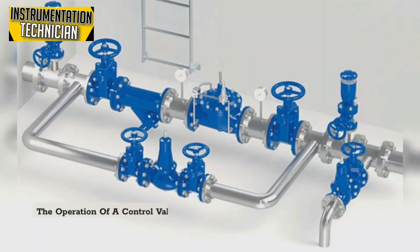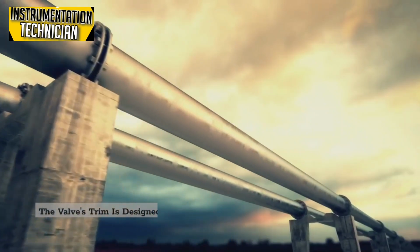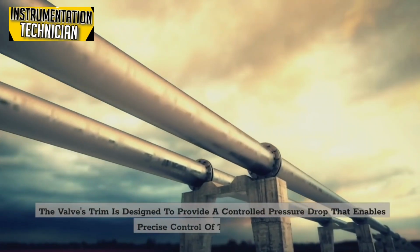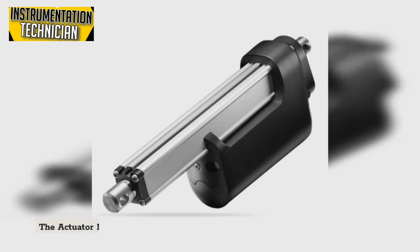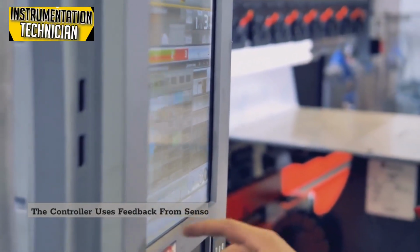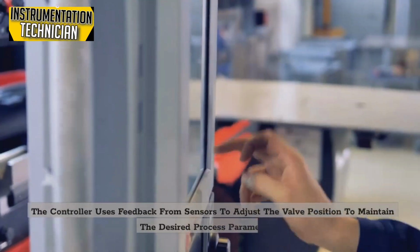Control valve operation. The operation of a control valve involves a complex interplay of fluid dynamics, mechanical engineering, and control theory. The valve's trim is designed to provide a controlled pressure drop that enables precise control of the flow rate. The actuator moves the valve plug in response to a signal from the controller. The controller uses feedback from sensors to adjust the valve position to maintain the desired process parameters.